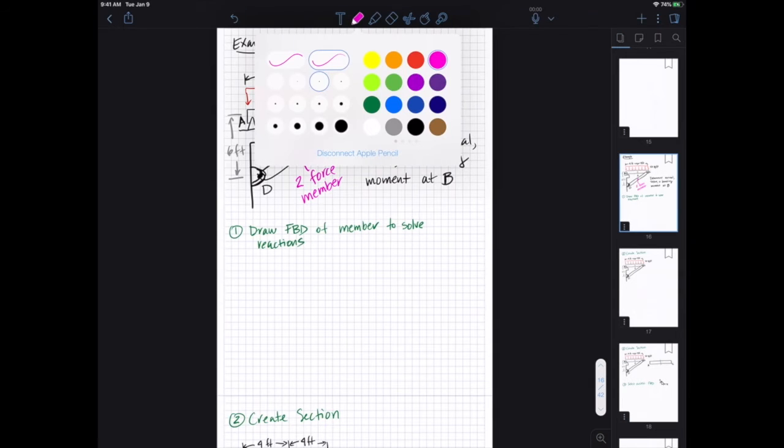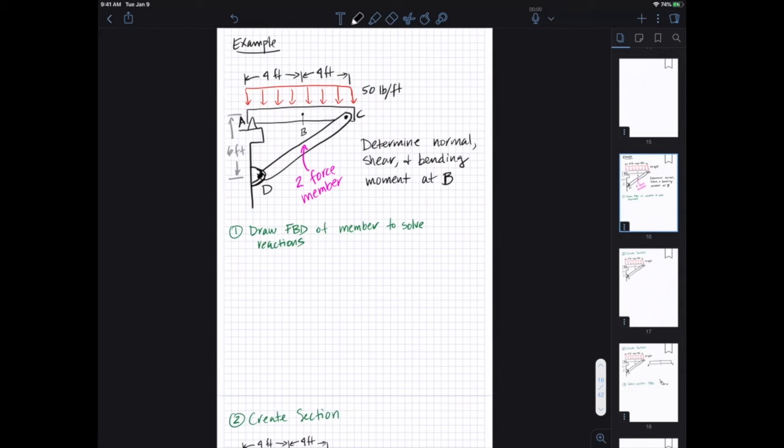So we'll start first with the free body diagram of member AC and see what we get. You can pause and try and do it on your own, or you can follow along. At point A, we have a pin, so we know we have an AY and AX. At point C, we know we have force CD. And we know, for example, FCD is on a 3, 4, 5 triangle, right? By definition, with the geometry given in the problem.